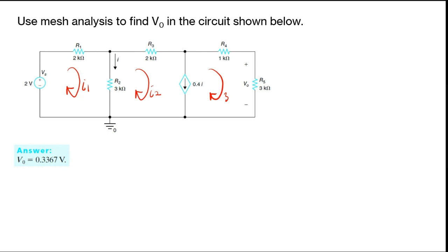So, how many equations do you need to come out with for these 3 meshes? 3 equations, 3 meshes, 3 equations. If there are 2 meshes, 2 equations. But it's a super mesh, so isn't it one together? Indeed it is together, but you need to calculate the node 0 here. The node 0 equation here. So node 0, here we call node 0, where the super mesh happens.